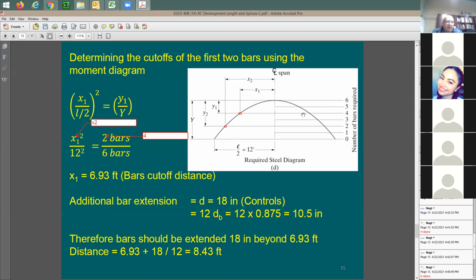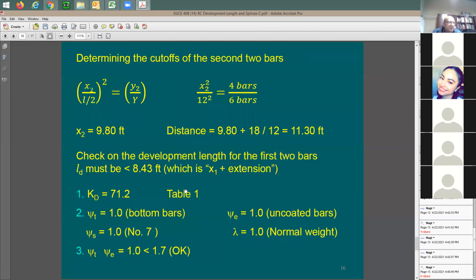And maybe it's going to be a good idea to stop 2 rebars at a distance of, as it says here, 8.5 feet from the center. So at the end of the day, you're going to have 2 rebars running from here to there. Additional 2 rebars running from here to there. So you can call them here 4 now. And then 2 rebars running from here to there. And of course, you extended 1.5 foot from each side just to follow this requirement of the code. So, okay, good. At least you start here to reduce the amount of steel that you're using to save a little bit.